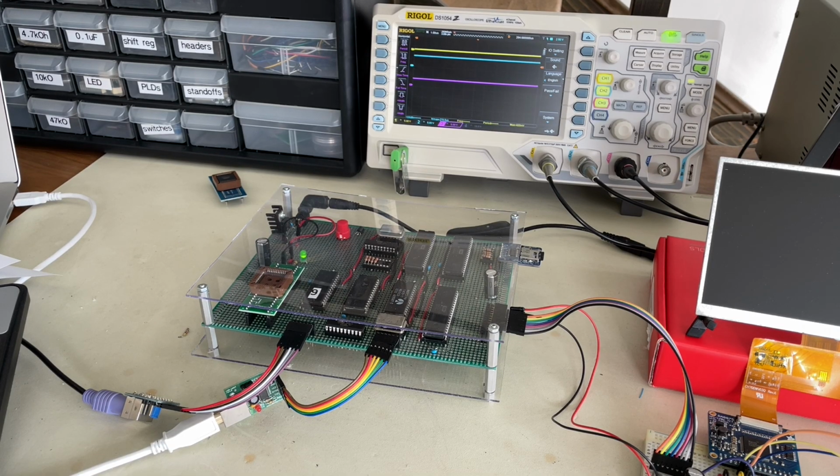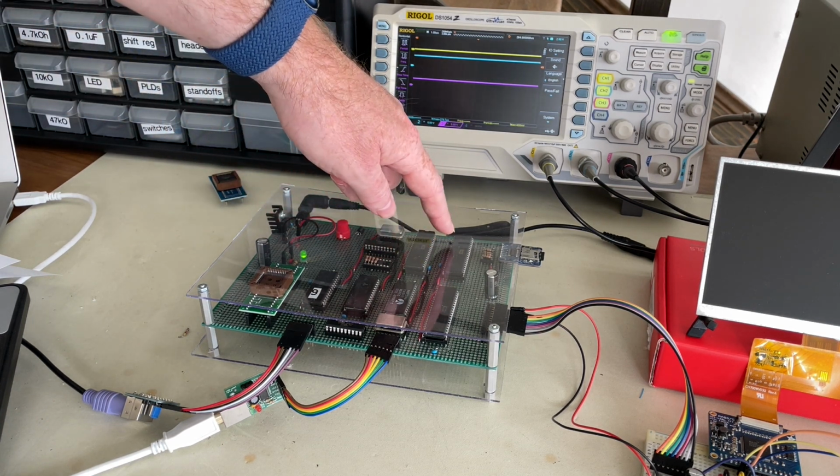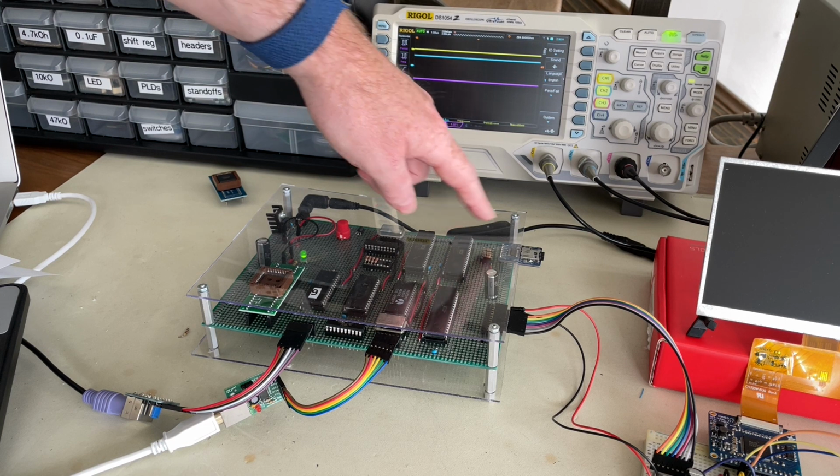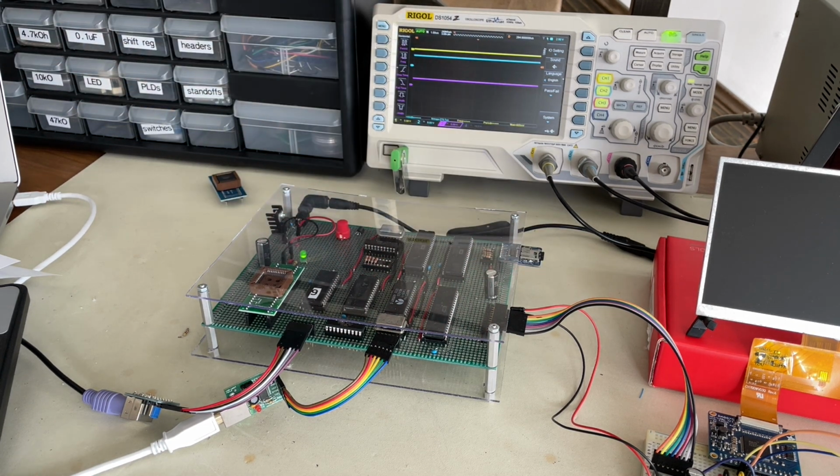So I've got my oscilloscope turned on now, which has a rather noisy fan, but hopefully that doesn't interfere with the audio too much. So I drive SPI for my video card and the SD card from parallel ports provided on the 6522s. So there are 2 6522s here. This one uses 1 port to drive the SD card. This one uses 1 port to drive the video card.